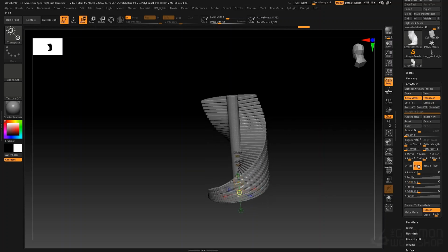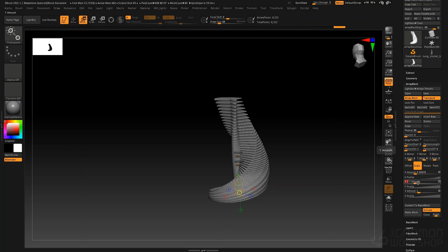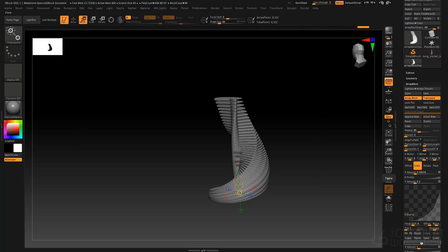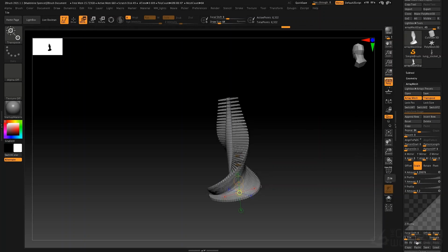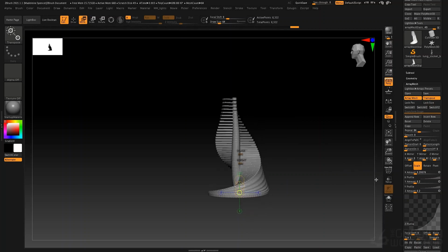We could also go to scale, and if our scale is set to 1 for X, Y, and Z right now, and I brought the scale down, we can change that scale effect here. So I will copy that curve, and then we will set the next slider here to 0.2, so we'll get the same scale in each direction. Open up that, and paste that same curve there. Close that, go to Z, set it to 0.2, open up the profile, and paste the curve once again, and that's going to make the X, Y, and Z values the same.